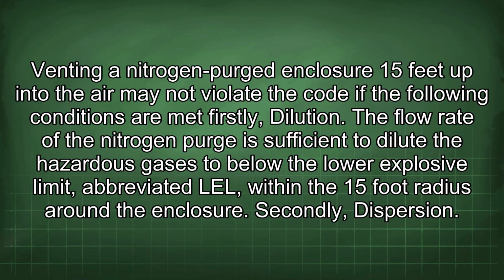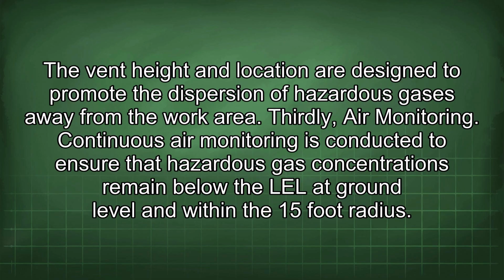Secondly, dispersion. The vent height and location are designed to promote the dispersion of hazardous gases away from the work area. Thirdly, air monitoring. Continuous air monitoring is conducted to ensure that hazardous gas concentrations remain below the LEL at ground level and within the 15-foot radius.